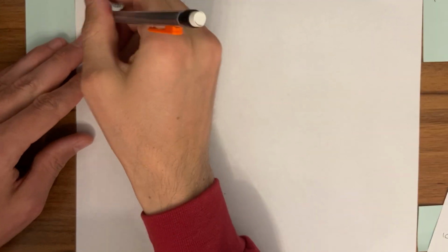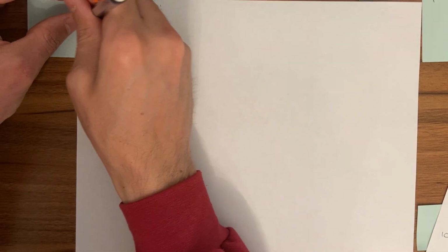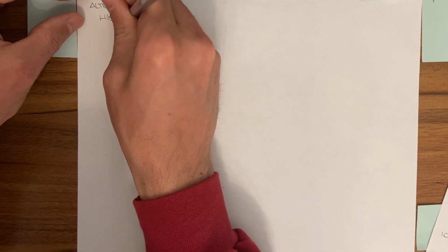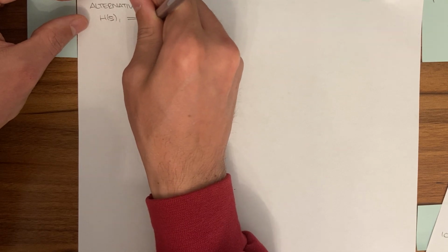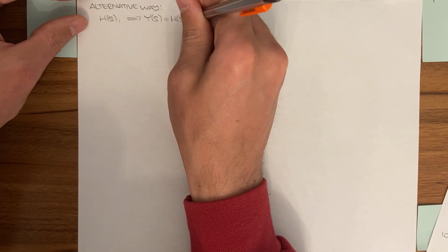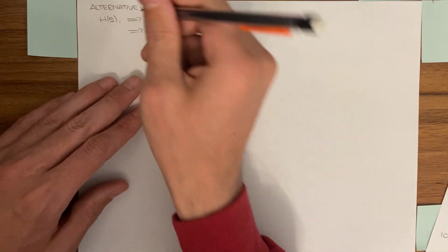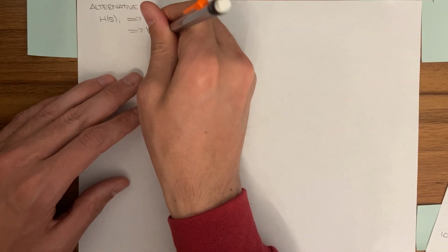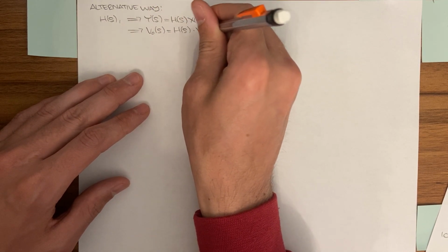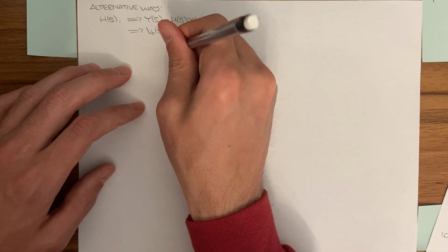So what you can do is you could set it up such that we know H(s), right? We solved that initially. So we also know that the output of a system, Y(s), is equal to H(s) X(s), right? So that would also mean that the output voltage in the Laplace domain is just the transfer function times the input in the Laplace domain, okay? So we know what the transfer function is. It's just 1 over 1 plus s.